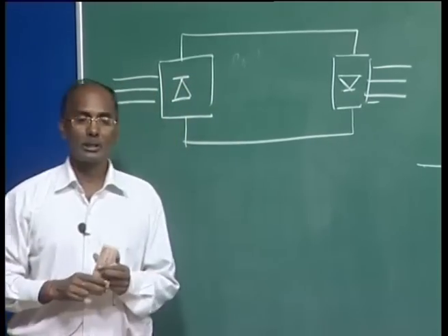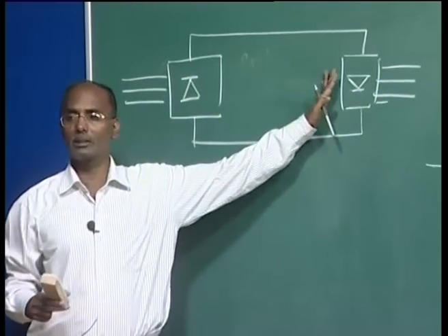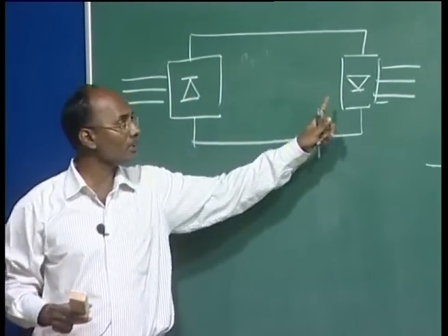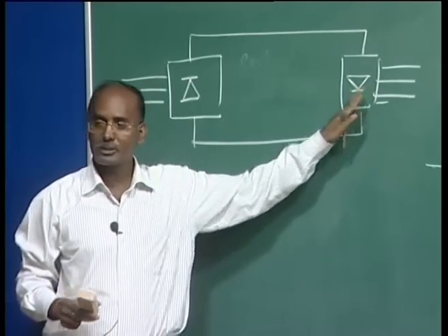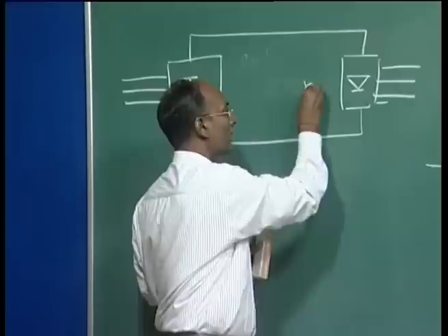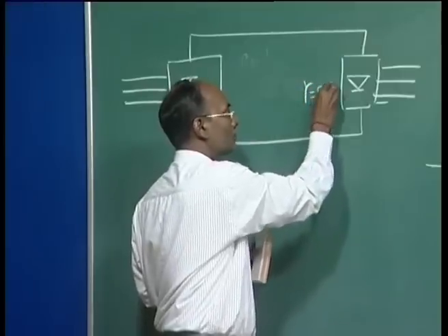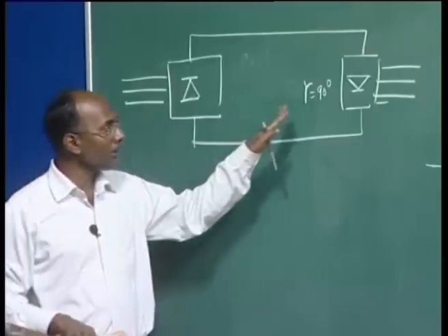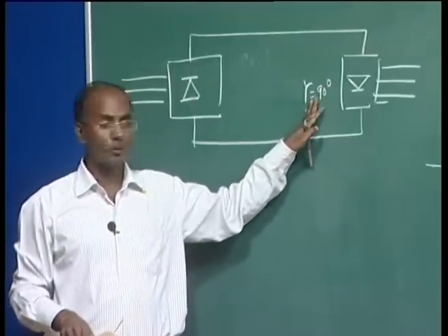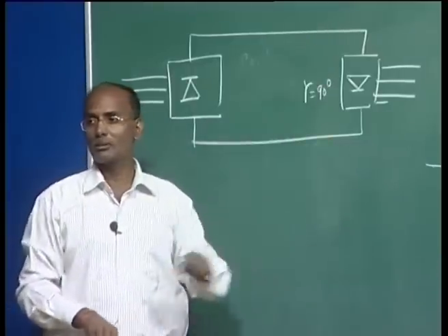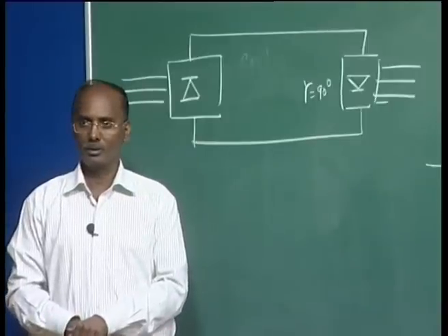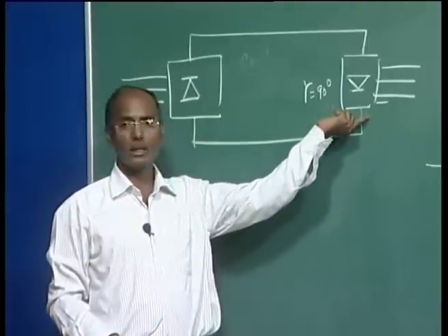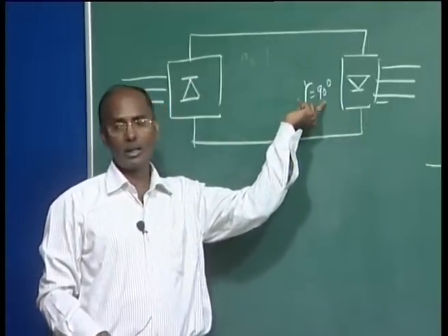Now, what we do here is deblock, meaning earlier it was not doing anything. Now, we are just giving the firing pulse to this, and especially we are maintaining gamma at 90 degree. If you are giving approximately 90 degree, what will happen? The voltage across this will be 0. You are just deblocking here, giving 90 degree, and it will be on.